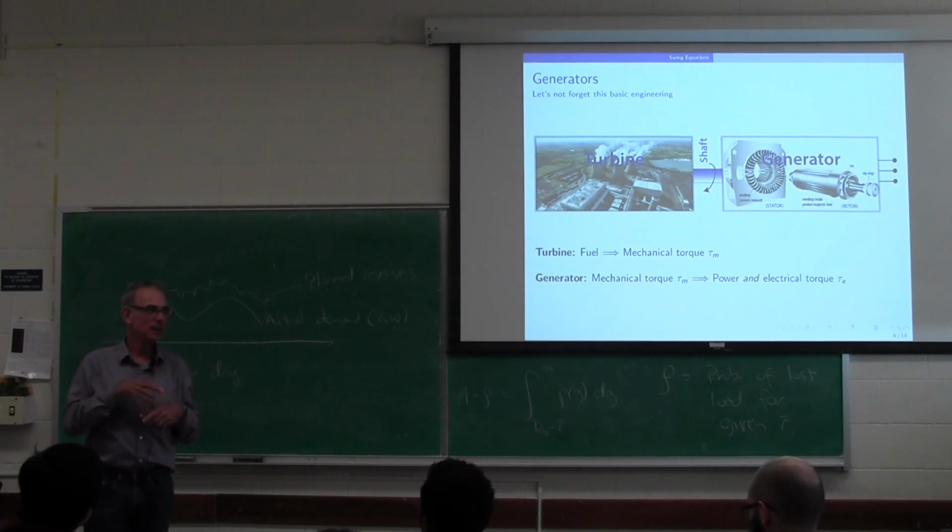And you've got a huge population, 100, 200 generators, and everyone has a different resonant frequency. But you only have to excite one of them, and that generator will kick itself out of the system automatically. It's not going to wait for that oscillation to happen. As soon as the frequency sags, it's been designed so it'll just shut out because of fear of resonance inside.